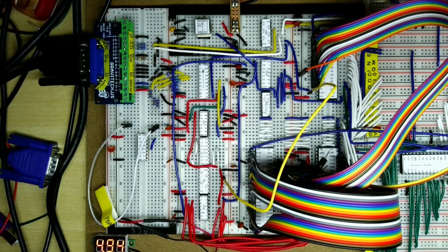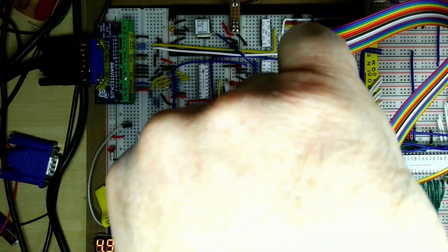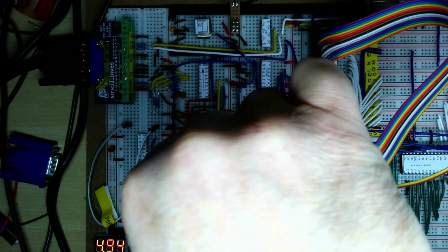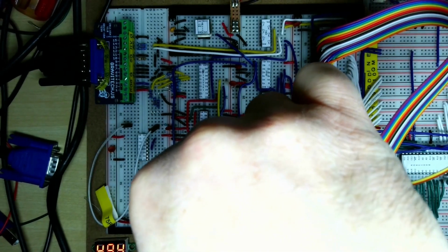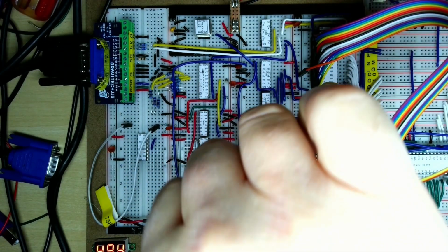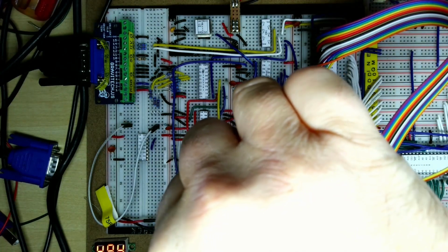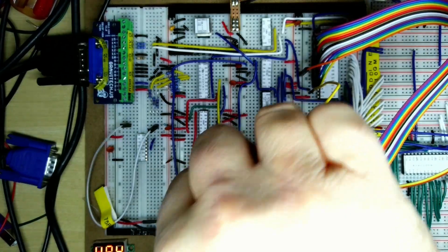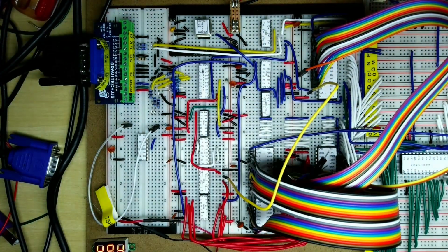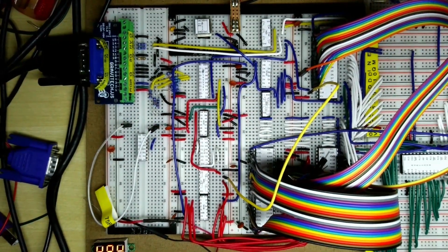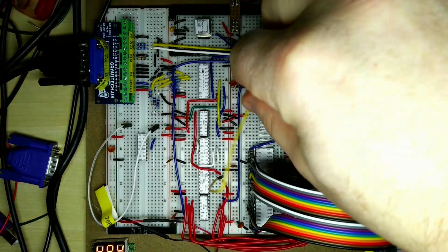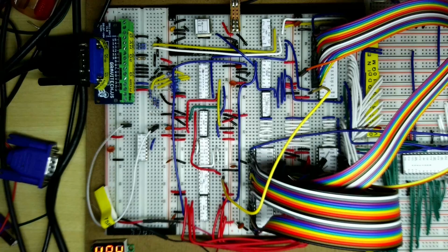And we're now going to change the input here to go to the other input of the exclusive OR gate. So we'll just put that in there. And now the output is going to go to the buffer, sorry, the multiplexer that we've got up here. So that's the change that we need to make. Fairly simple, a bit of a fly lead here you can see, but we will wire that in properly a little bit later on.